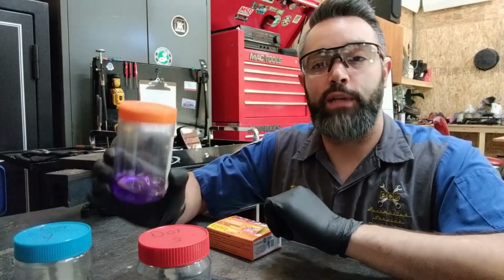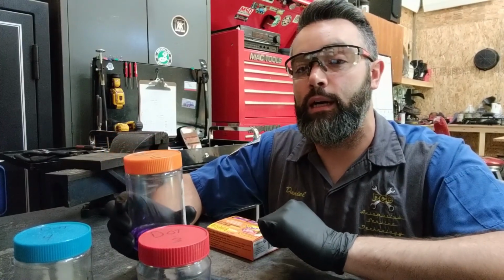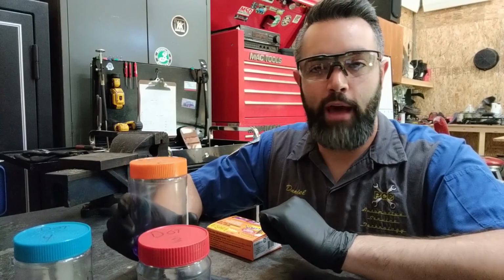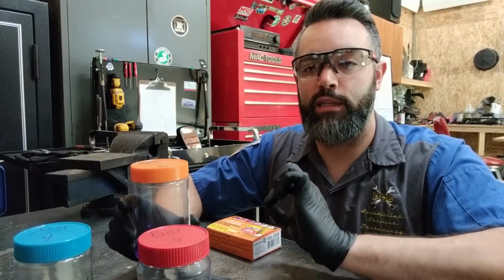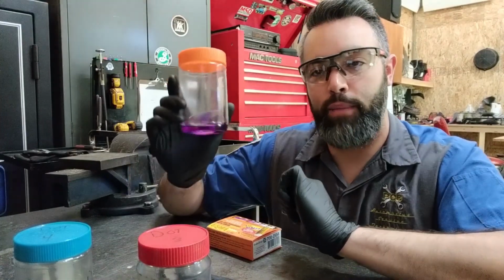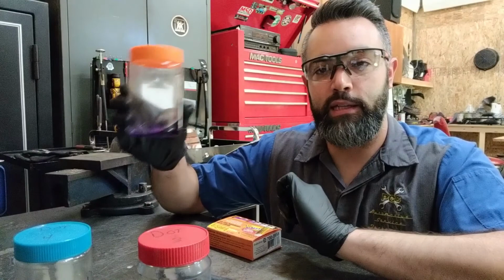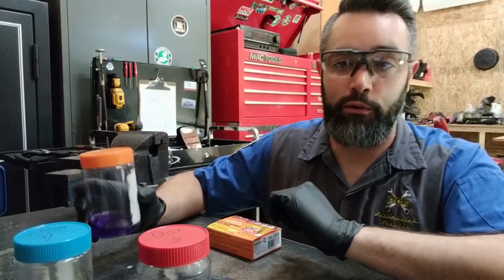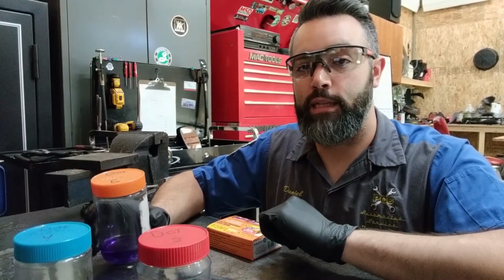One of the applications for DOT 5, other than a motorcycle, might be a classic vehicle, a classic vintage car. And if the owner of that vehicle replaces the seals in the system to where they are compatible with DOT 5 brake fluid, then this can be run in there and you don't have to worry about it absorbing moisture over time and having to continually replenish that fluid and service the system.